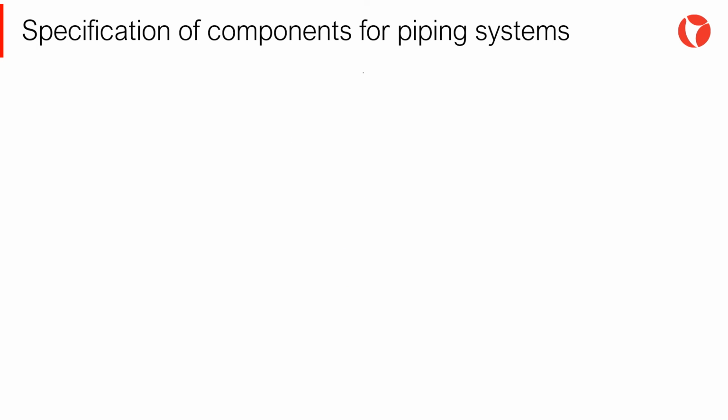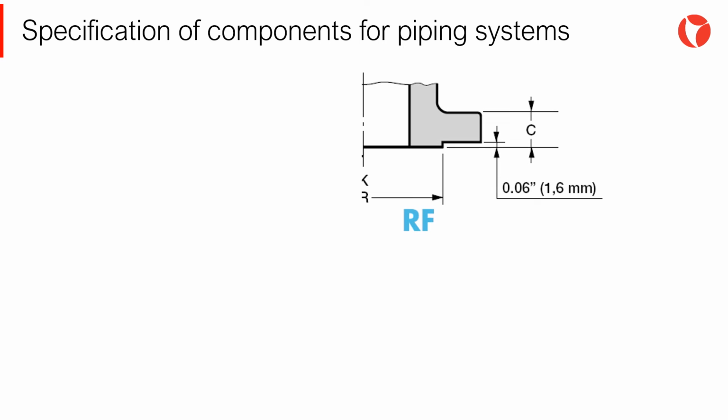There are several types of flange facings. They are selected upon the seal tightness requirement. The most used flange facings in pressure vessels are raised face flanges. This is the most common type used in process plant applications. It is referred to as a raised face because the gasket surfaces are raised above the bolting circle face.